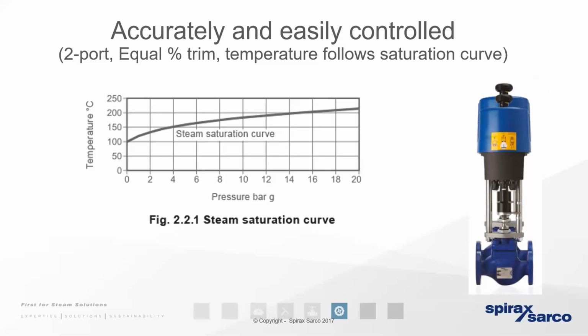So we need a 3-port valve with the 3rd port being the diverting leg. And it also means that because steam is a gas and moves in accordance with the pressure drop, we already understand that we don't pump steam. It flows in accordance with the pressure drop. But of course, we need to pump that liquid. So that water-to-water heat exchanger will require a little circulating pump on it to ensure that any unwanted energy can pass quickly away back to the boiler house.